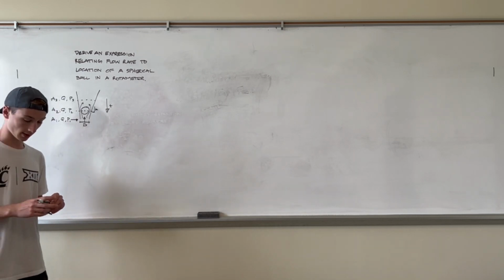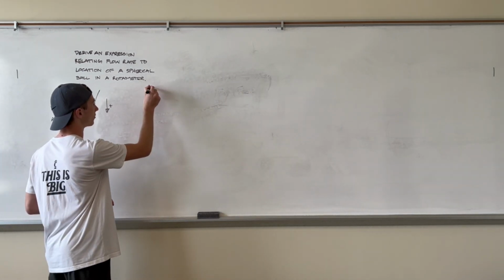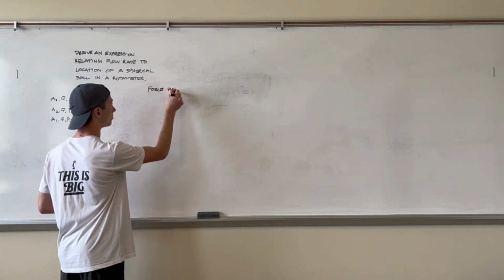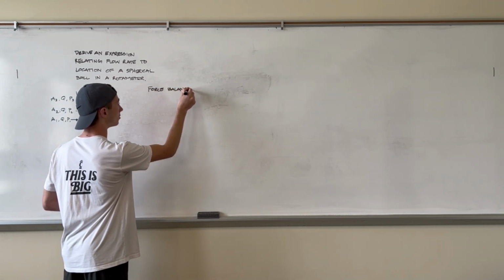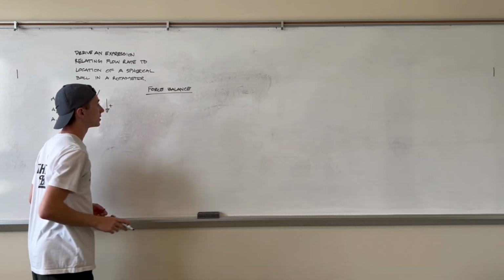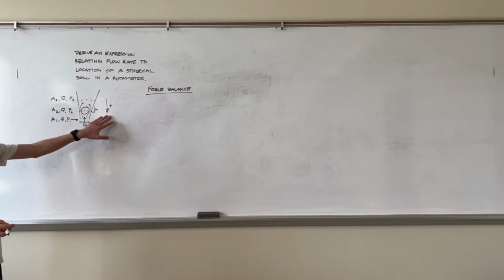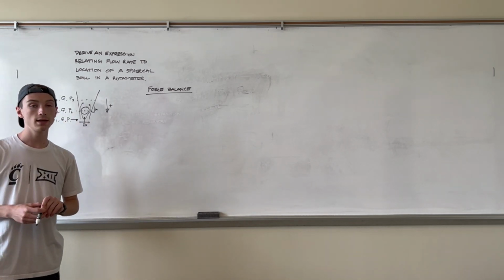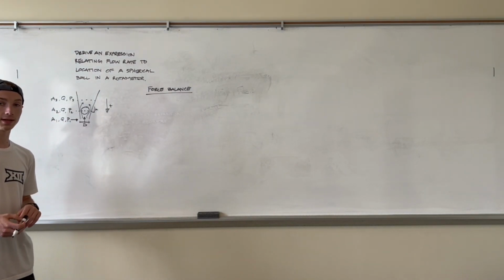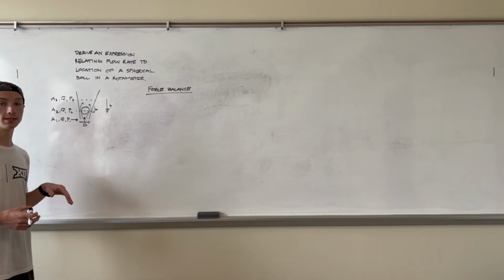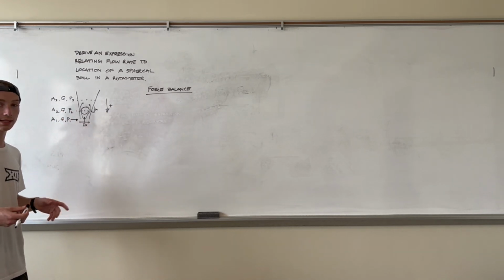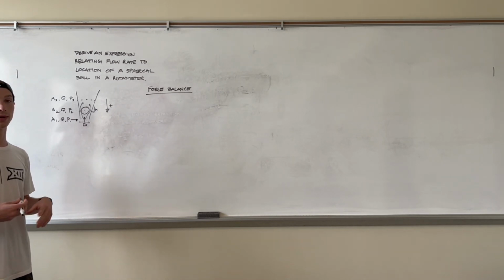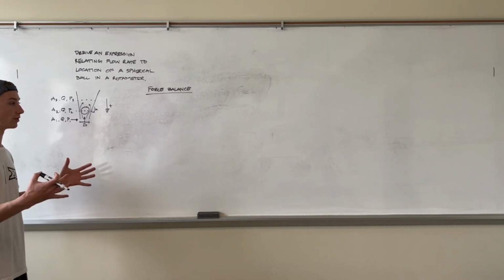Let's start by writing a force balance equation for the situation we have. If downward is positive, what are the forces we need to balance here? Well, the ball has some mass. It has some effective mass based on the density of the ball and the density of the fluid that it's in. Likely the fluid is going to be air, but just in case we're going to generalize and just say it's a fluid for now.